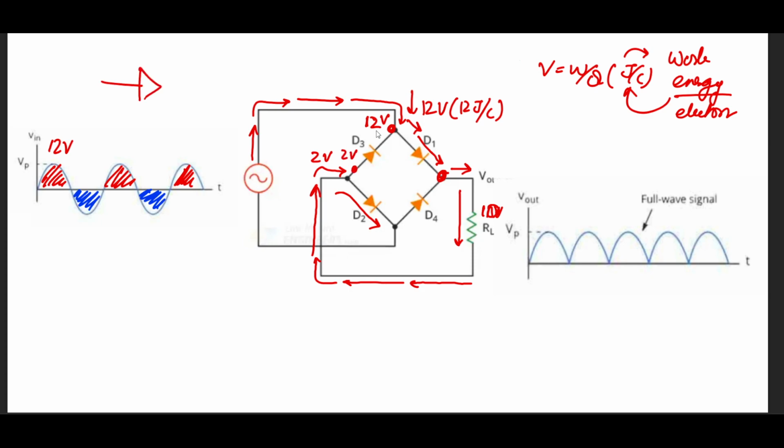Now we notice that the diode in this condition will be considered reverse biased, even though both voltages are positive, because this one is higher, this one is lower. The current cannot flow from a high potential to a low potential in the opposite direction of the diode. It cannot happen. So that is why the current will not choose this path. It will reject this path and go towards this path instead, which has a connection with the supply of 0 volts, because most definitely the current has to flow from a high potential to a low potential, right? So this diode path is rejected by this current, and it flows back to the supply like this.